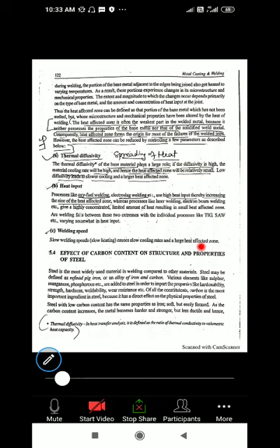That is the heat affected zone, because it neither possesses the property of the base metal. Whatever the property of that base metal is, this zone does not have it, because the microstructure has changed compared to the base metal. In the heat affected area the microstructure is changed. Once the microstructure is changed, obviously the mechanical property will also change. But the base metal is not affected by the heat, so no property changes will be there.